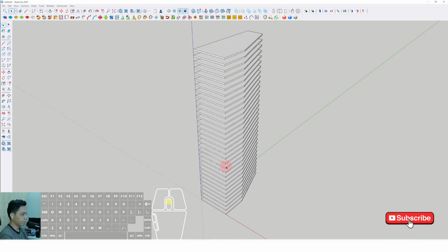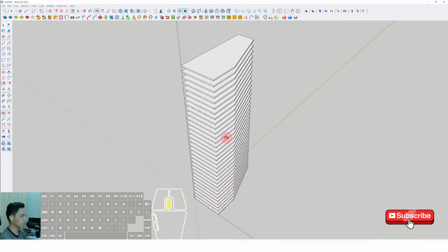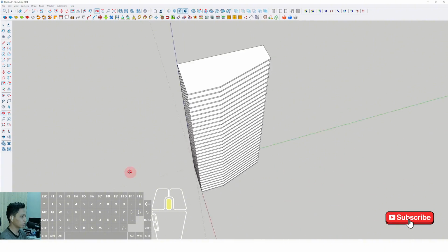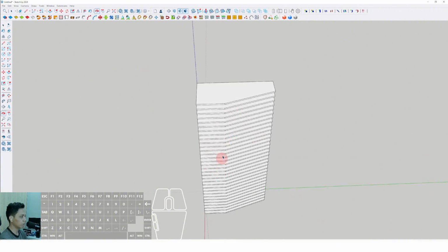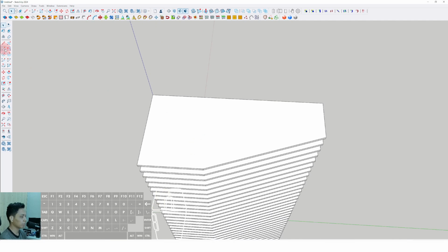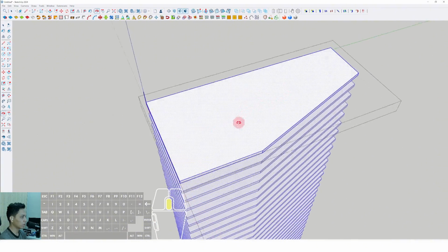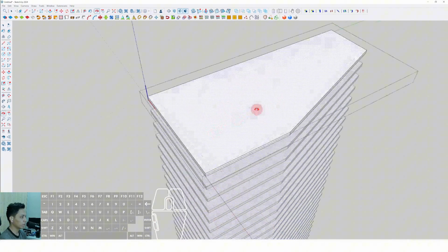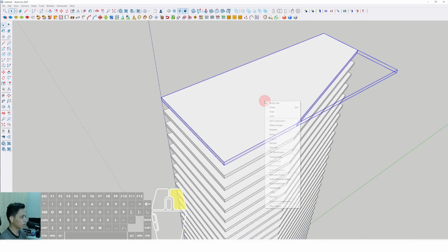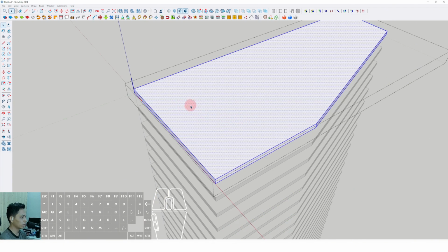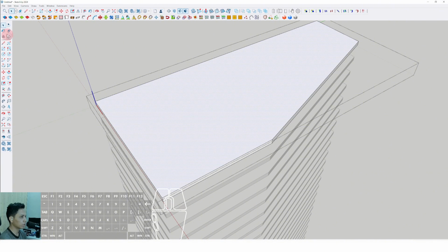Okay, then this is the trapezoid floor plan of this high-rise building. Then we can make another element, a core building approximately in this area, or we can make the core building using the slab. We can right click and make unique slab, click the surface and use the offset tool to offset it inside, around 8 meters,